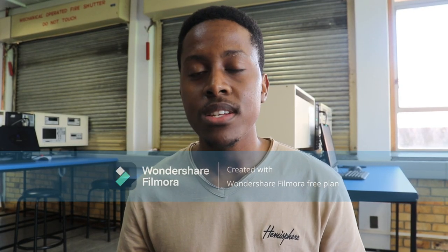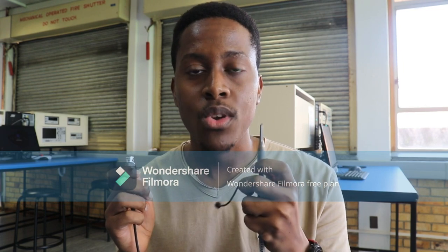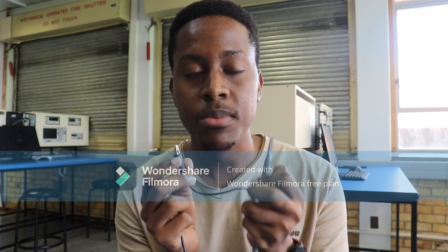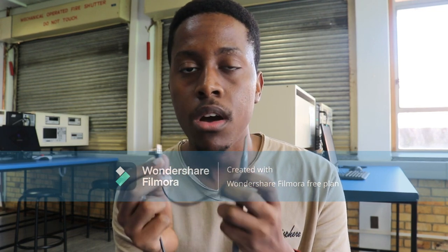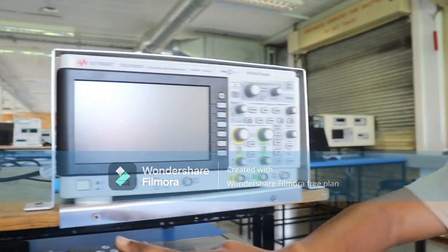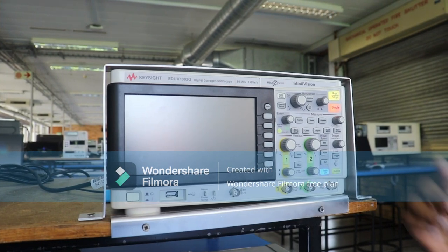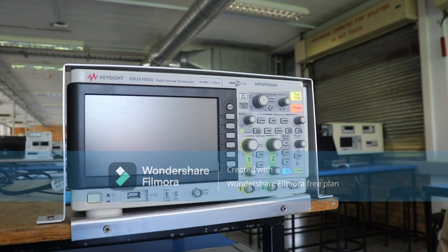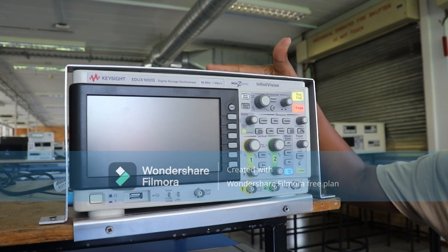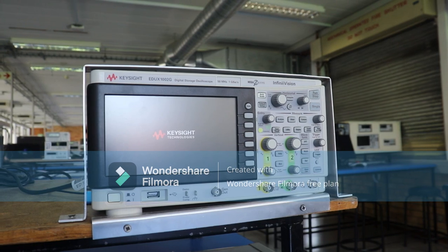Now, moving on to our oscilloscope. For this machine, we typically use a BNC connector and your scope probes. This has 2 different terminals which you can hook up to the positive and negative terminal of your circuit. Now, if we look at our machine, how you turn it on is simply pressing this button and wait for the fireworks to show up. This machine typically takes a bit of a while to warm up before you can start seeing the signal.